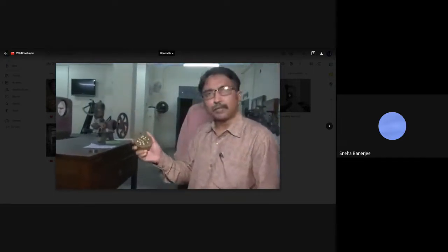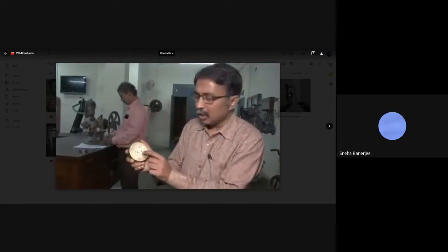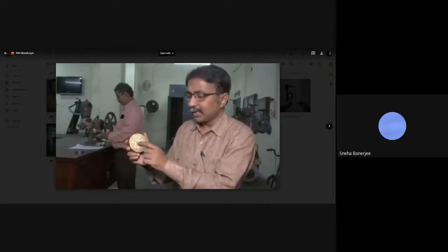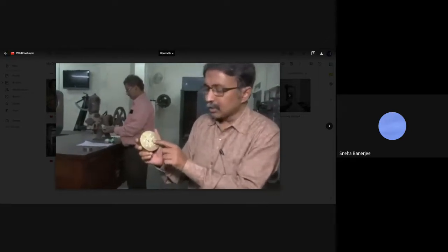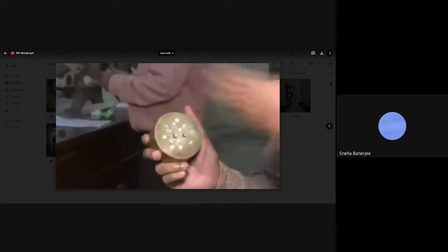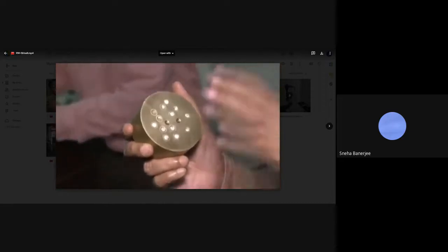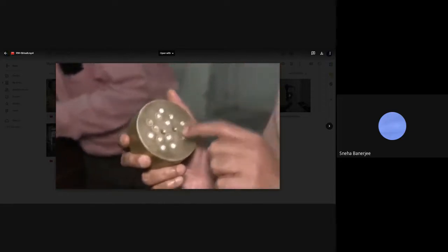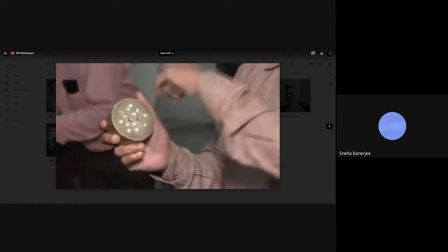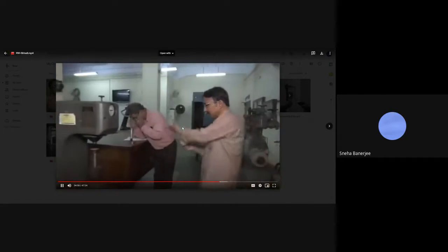Now we will use the optical microscope to find out the diameter of this impression. This is brass. On this we'll be getting a number of data points, because we can measure the diameter in different directions, maybe 2, 3, 4 times. We will take an average, and that average value is the representative value for brass. Then we will find out, corresponding to that average diameter, the Brinell hardness number of brass. Let us try that. He is doing it.